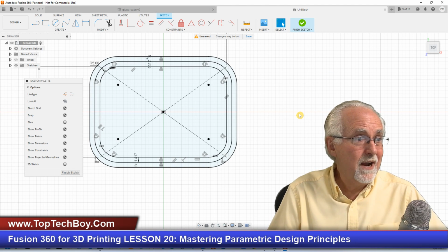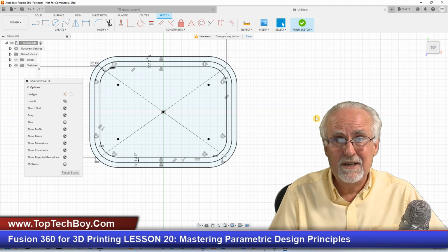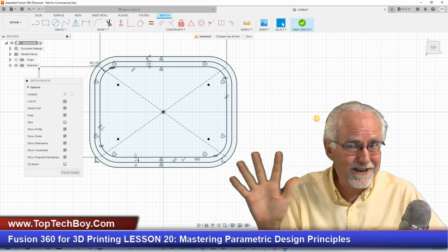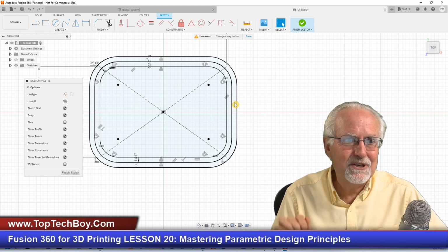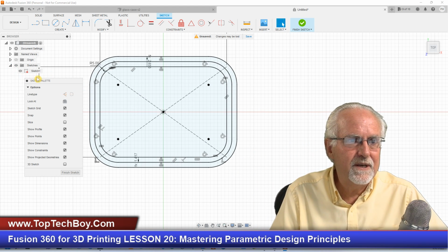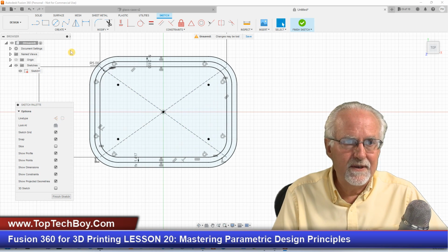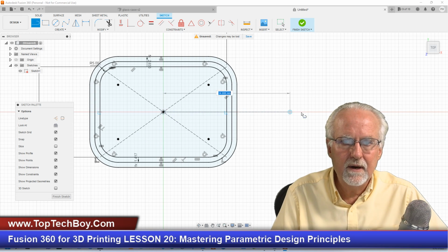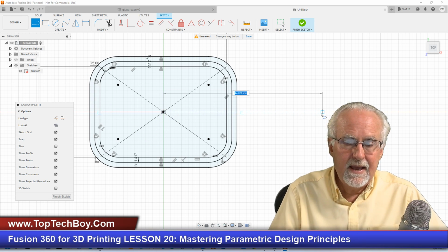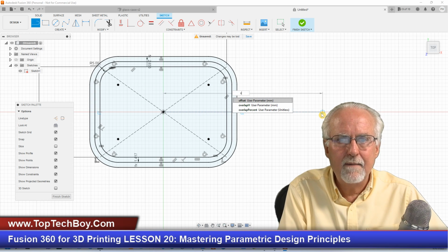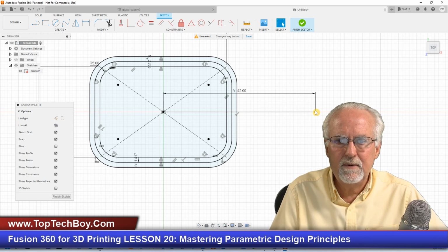Now guys, I tried for 30 minutes to copy and paste this thing and have it be fully constrained, and I just couldn't do it. And I just hate designing things that are not fully constrained. You can see we're fully constrained here. So I'm just going to redraw this again really quick. I'm going to give myself a construction line. I come here and then I come out. And then how far do I want to come out? By offset. Remember, I defined that offset. Okay, boom, that gives me that position there.